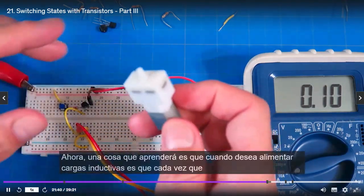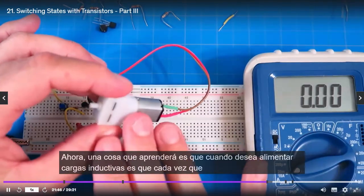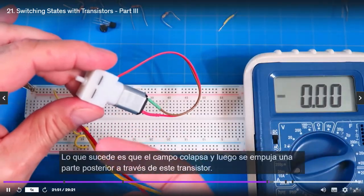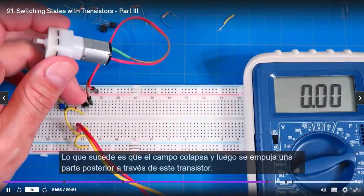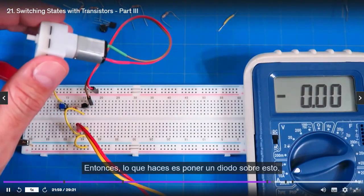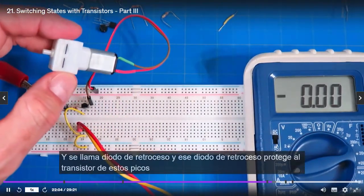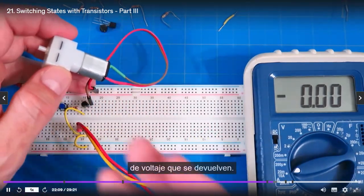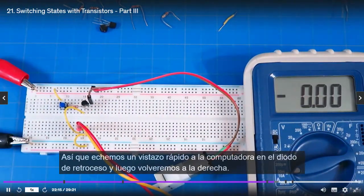But not bad. Okay, now, one thing that you'll learn when you want to power inductive loads is that every time this motor turns around, the field collapses and then a back EMF is pushed through this transistor. So what you do is you put a diode across this, and it's called a kickback diode, and that kickback diode protects the transistor from these voltage spikes that get thrown back. So let me show you real quick, because this is an important little tidbit. Let's take a look on the computer real quick at the kickback diode, and then we'll come back, all right?